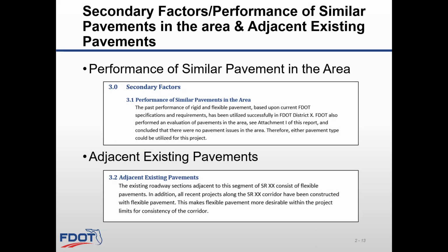A secondary factor to consider in the analysis is the past performance of similar types of pavements in the area. This is a valuable guide provided the conditions are the same. Caution must be urged against reliance on short-term performance records, or on long-term records for which the pavements might have been subjected to much lighter loading for a large portion of their present life.